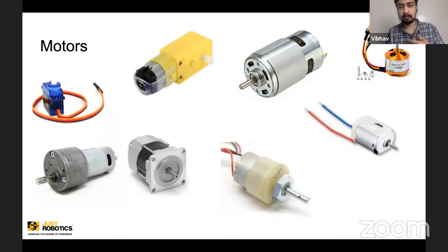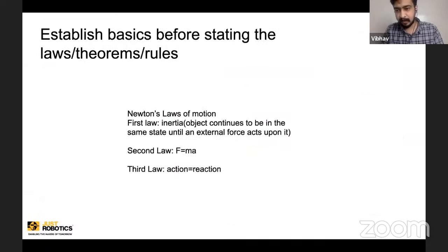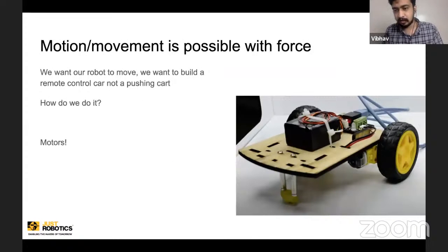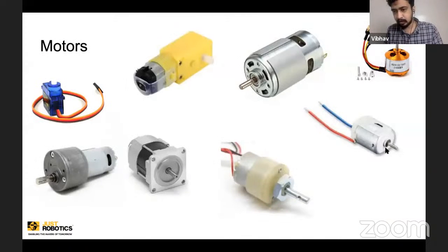But in our robots, we use this kind of battery where there is no voltage control. So the RPM of this motor remains constant, say 1000 RPM. These base motors are in the order of 1000 to 2000 RPM. This is the same motor that you can see here. And this yellow color part is the gearbox. It has a reduction gear system. It will convert these 1000 to 2000 RPMs to 100 RPM.